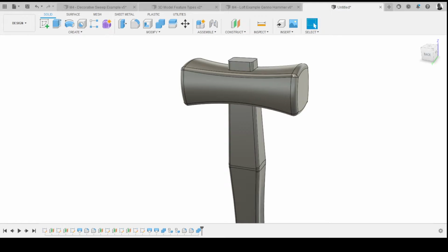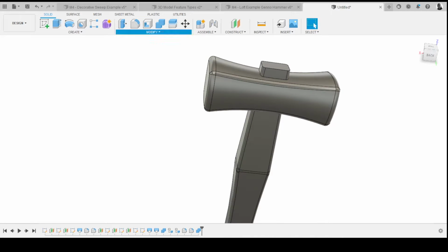We've got a function in Fusion where you can split bodies using other tools. So you can use planes, you can use faces, you can use sketches to cut bodies in the way that you want. Under the Modify menu, and this is a really useful function, again, you'll use lots if you haven't used it before, we've got the split body function, okay?